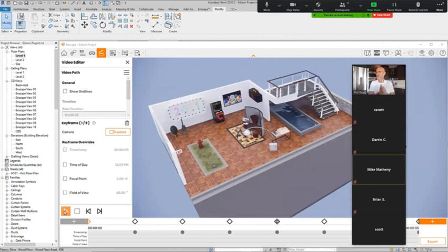So what we have done in less than 30 minutes is we've shown how to place keyframes, to create moments of rest between keyframes, to explicitly control the Enscape camera from Revit, to then export the XML file in order to create jump cuts between individual sequences so that when we render, we don't have to open and close them manually and wait for each sequence to render. It's not interesting. We can just do it all as one sequence.